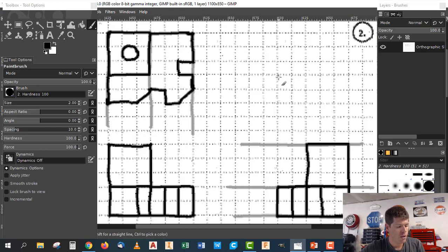The good thing you guys will see later on as we do this is that in your CAD software you can basically drop these views on after you 3D model, and the computer will draw these views along with all the hidden lines and the visible lines. So we're going to do less and less of this as we go through the semester, but it's important that you understand what this language is and how to do it.